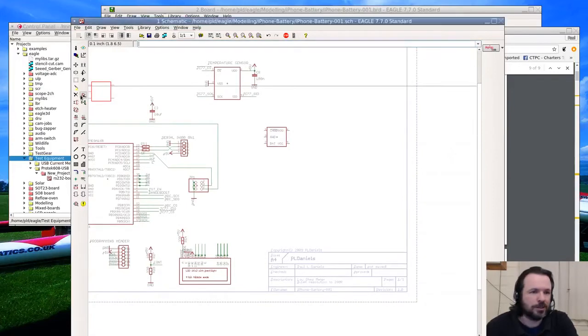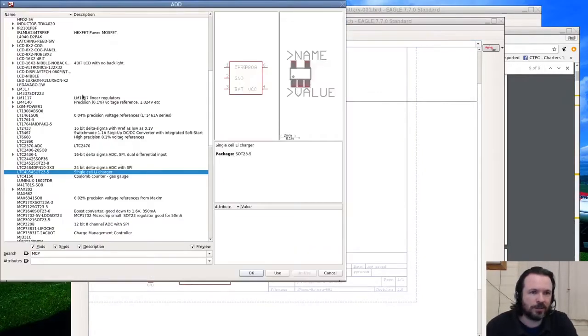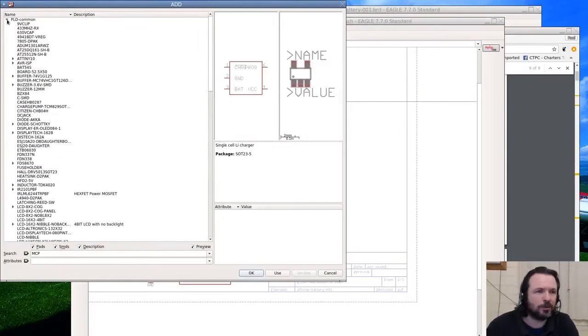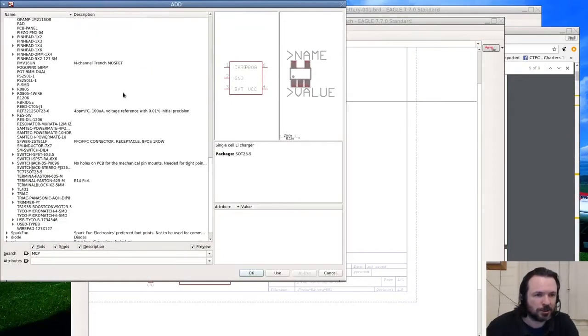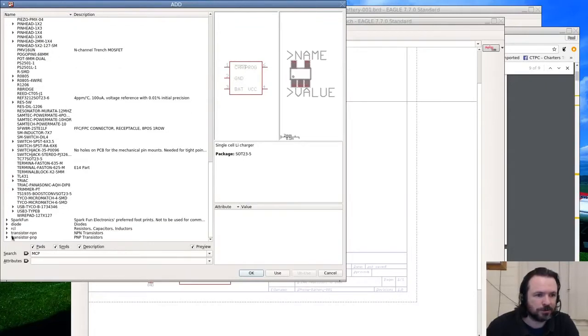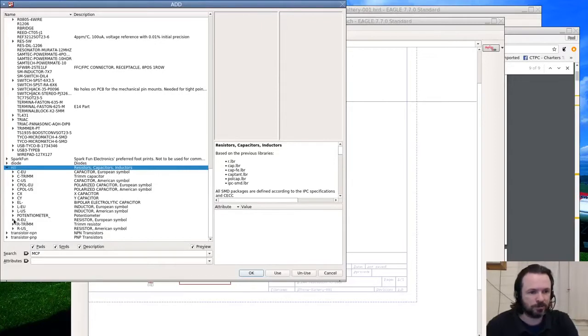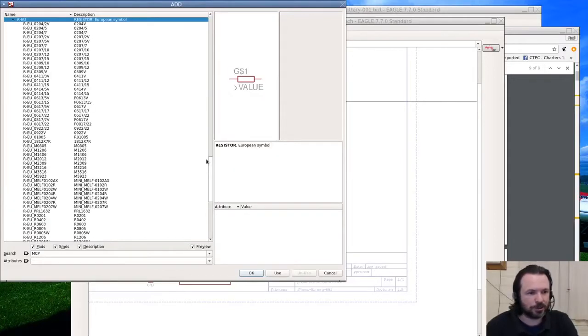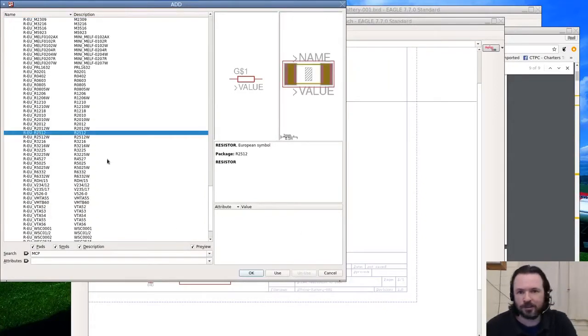Okay, for discharging it, I'm going to go with what I used in the little discharger that we were looking at just before, and that's going to just be a bunch of 2512 resistors. They're also dirt cheap, and you can spread them out to get a bit of a heat distribution effect. 12, that'll do.